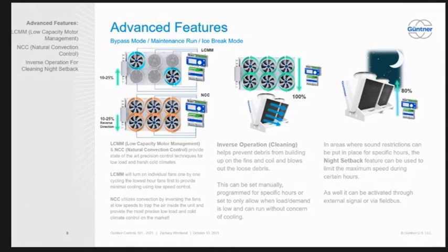But what I've picked up a little bit is that on the CO2 side, if you lose heat, it could be bad for the system. And what we've done is, in our controls, we can tell if the fans are spinning due to natural convection. Because in the winter, when it's really cold, if there's heat in the heat exchanger, that heat goes up and can force the fans to spin. Well, if our controller senses that, it'll actually spin the fans backwards at a very low speed, trying to lock that heat inside the unit, so you're not losing heat due to natural convection.